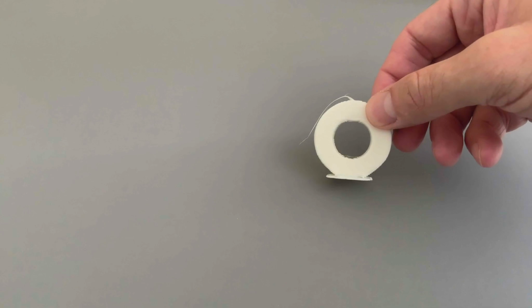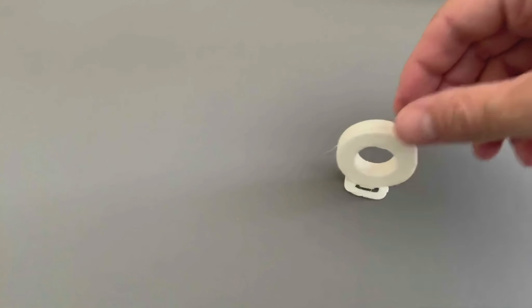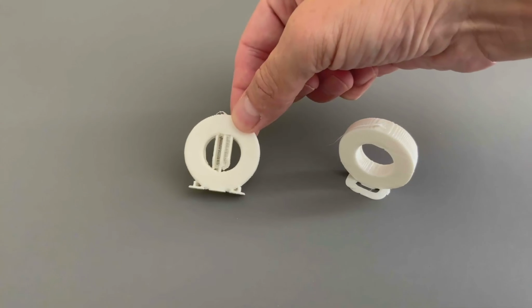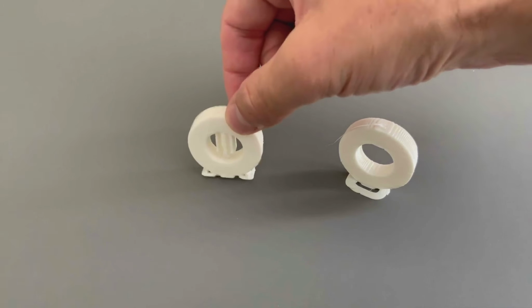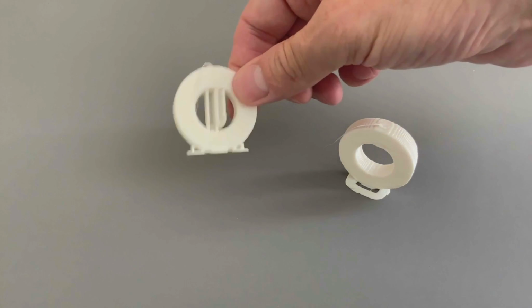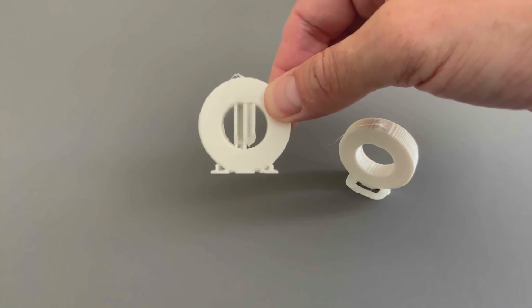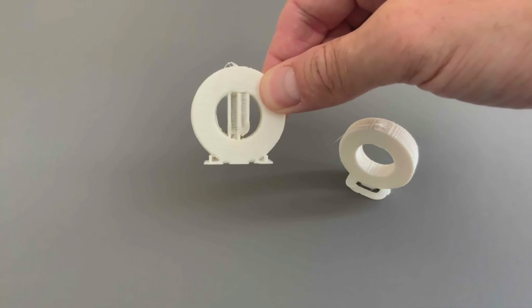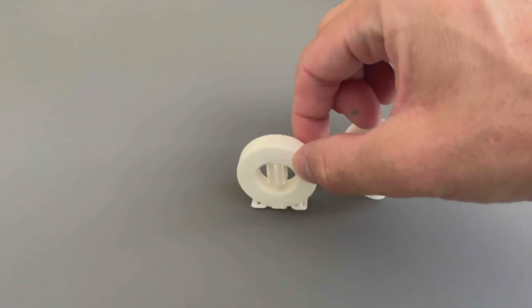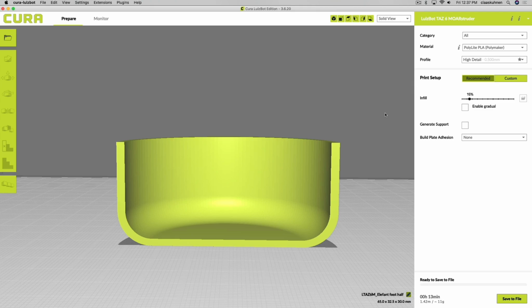And here we also have the O without the inner support. You can see how the top is actually more flat. And here we have the O with the support inside. That then helps to make the O a little bit bigger. One tip for rings, in particular when they're smaller, you can also use a drill and then clean drill those cylindrical shapes to be perfectly round. Well, we will go into how to print holes today too. Let's take a deeper look at the build plate adhesion and also the orientation one more time.